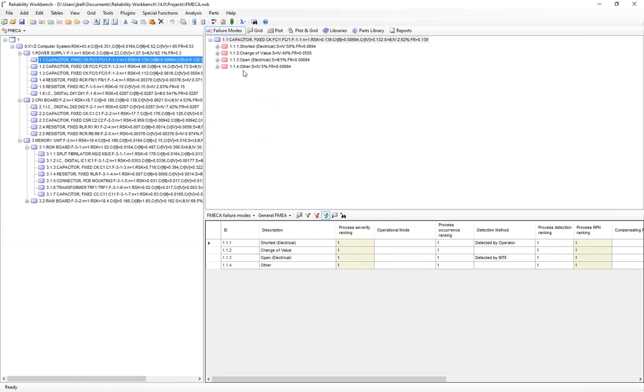The system can fail in different ways, and some of those system failures are worse than others. So the failure of the capacitor could produce different effects on the system depending on which failure mode. So the point of all the FMEA methods, FMEA, FMECA, FMEDA, is to figure out not only how the components fail and their impact on the system, but rank those failure modes to figure out which have the worst impact on the system. So again, we'll look at different ways of doing that.